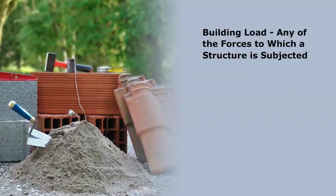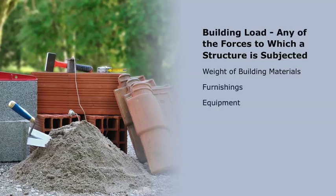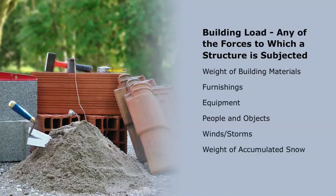The term building load refers to any of the forces to which a structure is subjected. The weight of the building materials is part of the building load, as are any furnishings or equipment inside the building. Building loads also take into account people and objects that move into and out of the building. In addition, building structures are designed to accommodate winds, including storms, the weight of accumulated snow, and earthquakes.